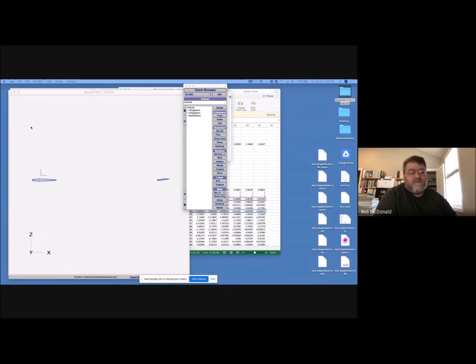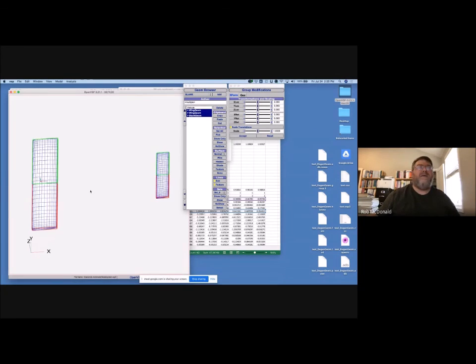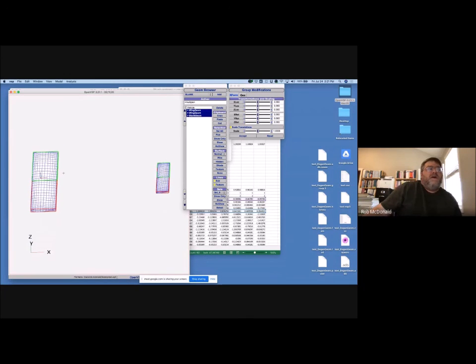Whereas somebody who came from a Northrop background would call it a flying wing. From the physics of just an airplane, just looking at it from the outside, they're the same thing, right? And what I want to really get across here is, for an airplane to be stable and lift, you need a down force aft of the CG. You need a down force aft of the CG.